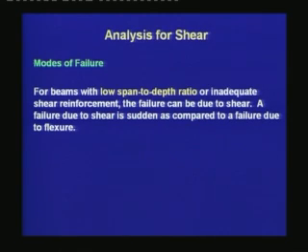Next, we are studying the modes of failure due to shear. For beams with low span to depth ratio or inadequate shear reinforcement, the failure can be due to shear. A failure due to shear is sudden as compared to a failure due to flexure.